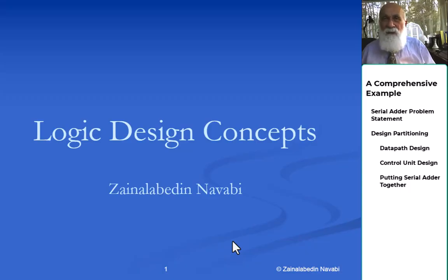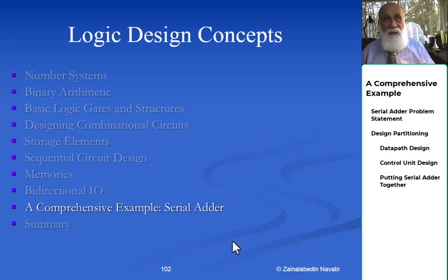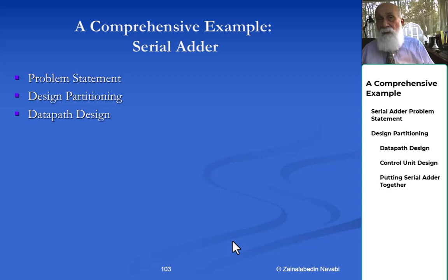All I'm going to be doing is a very simple serial adder, one that takes data inputs from its A and B inputs, clock by clock, and in 8 consecutive clocks, it will be adding those data together. After 8 consecutive clocks, it will issue a ready signal and generate the output, an 8-bit output. That was the problem statement. Okay, how do I go about this?